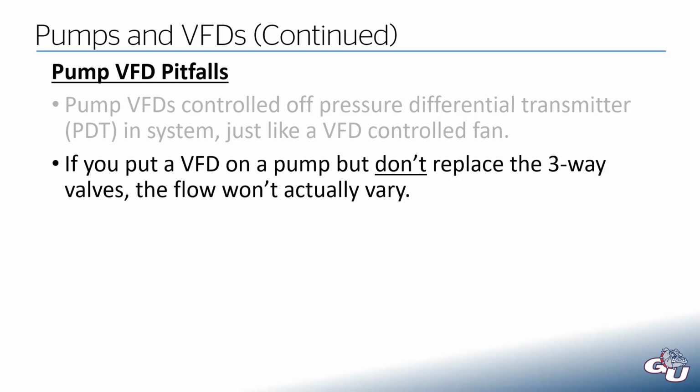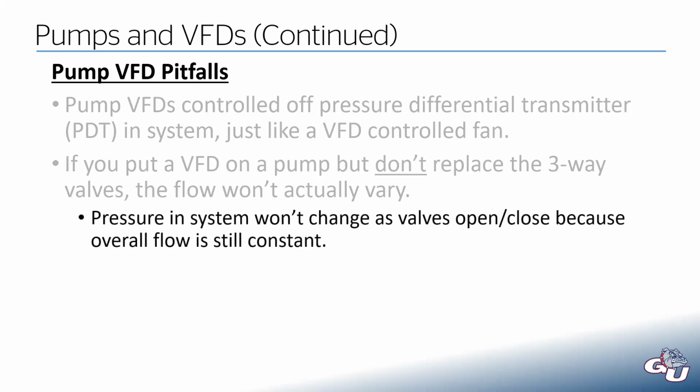Because that VFD is dependent on the changes in the pressure of the pipe. But if you have all three-way valves, that means they're all constant flow and you won't see any pressure changes and the VFD won't do anything. So the pressure in the system isn't going to change as those valves open and close because the overall flow is still constant.